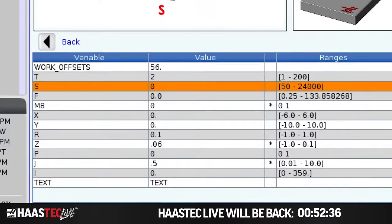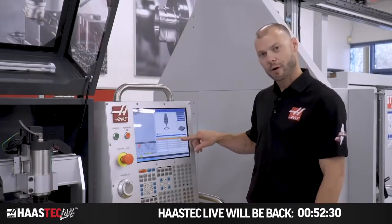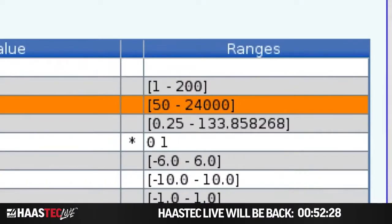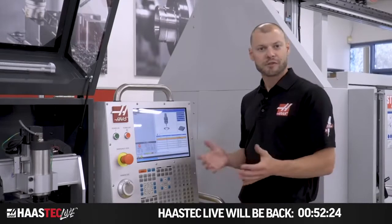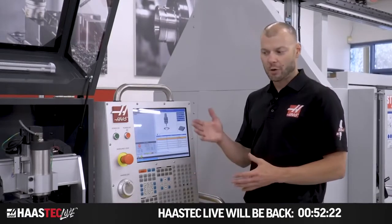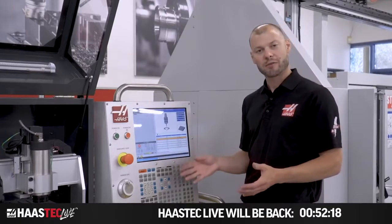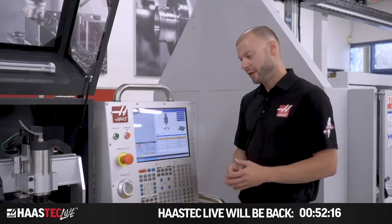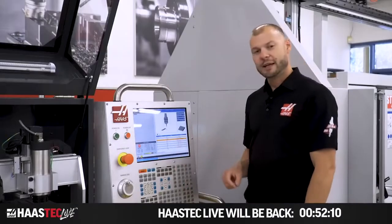Now it's asking for my spindle speed. How fast do we want the cutter to turn? I have a valid range of 50 to 24,000, so quite a bit of range in there. I'm going to choose 5,000 RPM just from my experience, and I know that that won't be too fast for this machine. Since we don't have coolant, I don't want to melt the plastic, so I'm going to select 5,000 and press enter. Next, I need to give it a feed rate.